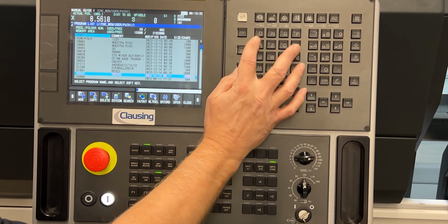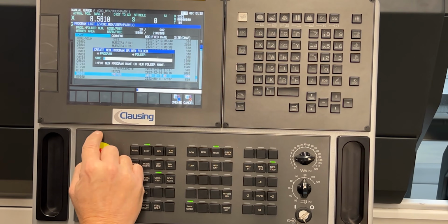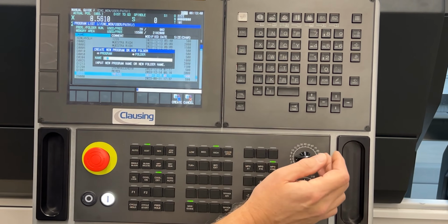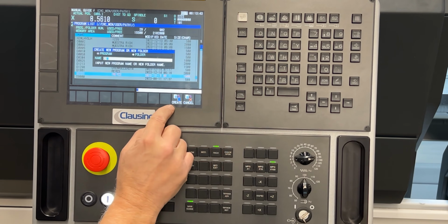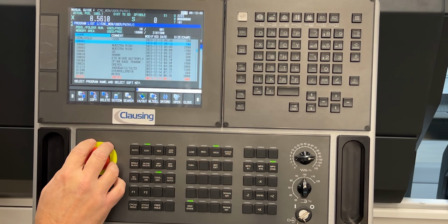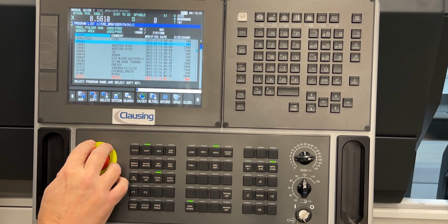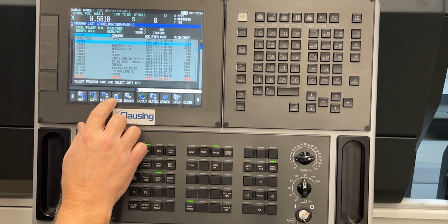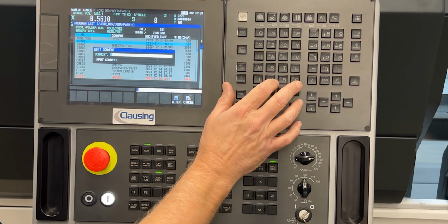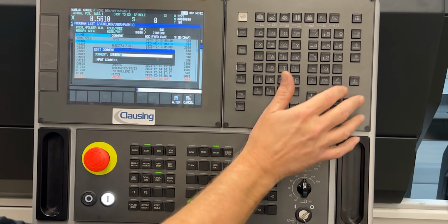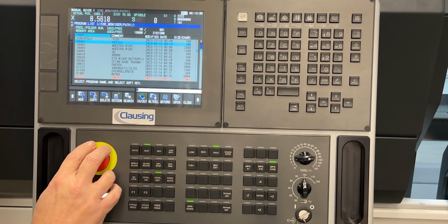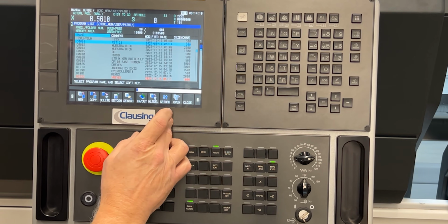So I'm going to hit new program first, then press O, and then I can just type in 1 because the leading zeros will be already inputted to it when I create it. So I'm going to hit create and so it shows you O0001. And then I can also edit the comment to give it now a name within the program itself. So we could do RST 1, 2, 3, and then alter, and so my program name is that. Once I've got that, then I'll go ahead and hit open.